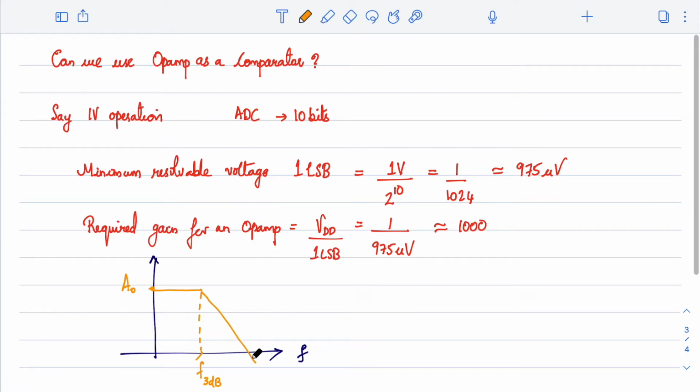We know that in the case of the two-stage op-amp, we had 2 poles, and by compensation, generally we work with circuits which are compensated. If it is compensated, it looks like a first order system having a single pole, and this defines the 3 dB frequency. The first pole, the dominant pole, will decide the bandwidth, and here you will have the unity gain bandwidth, UGB, also. Now let's assume that the unity gain bandwidth is around 100 megahertz, which is a reasonable value.